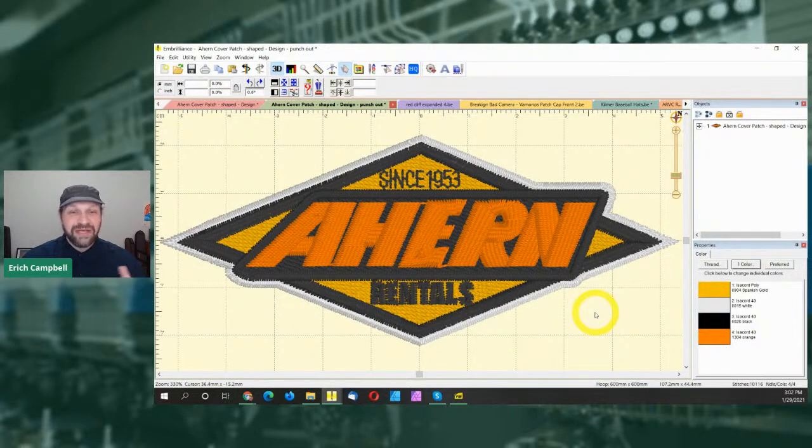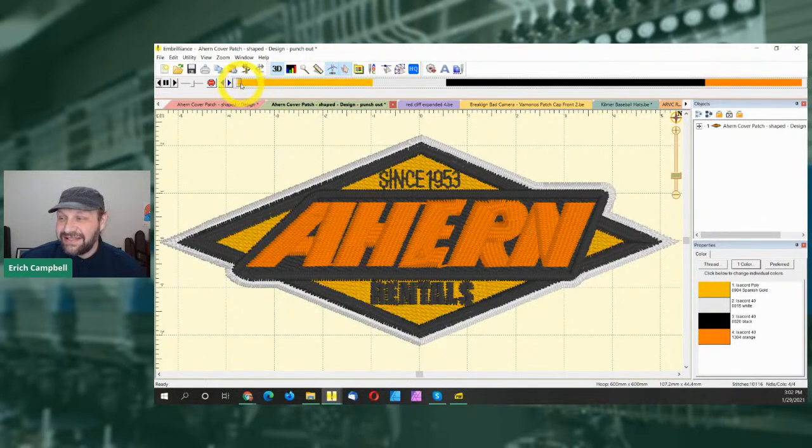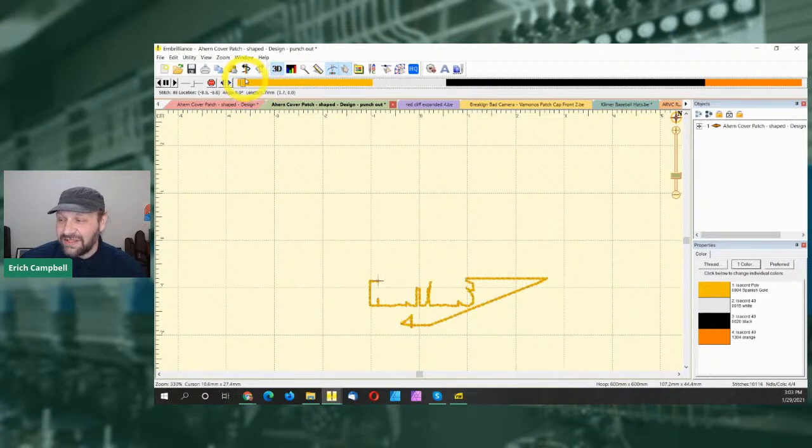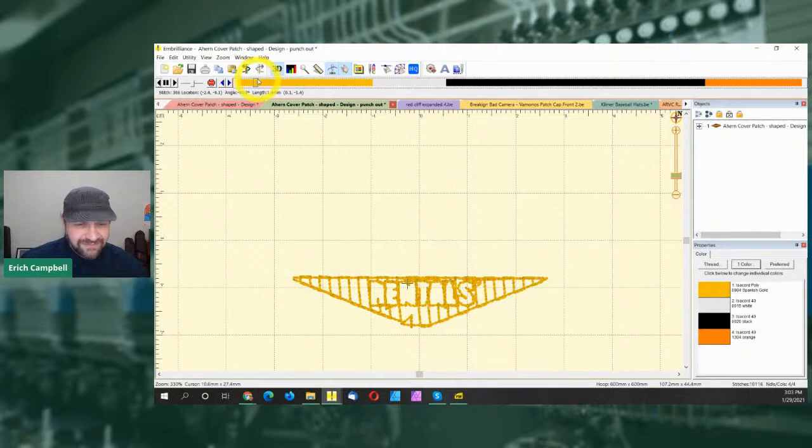It went up because now when we're going through this design, you're going to see that the design has to travel all over. First thing is, if I have an edge run and I left it automatic, it's going to edge run those inside holes. Awesome, right? We might want to turn that off. The second thing is, as it travels around to make the underlay, it's traveling over and over trying to get down inside of all these little gaps and cracks inside of these holes.